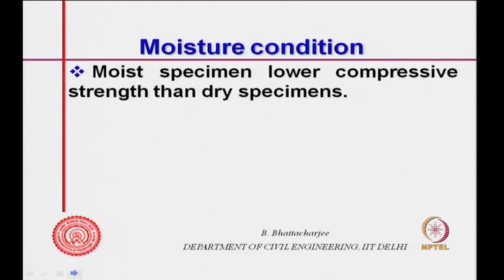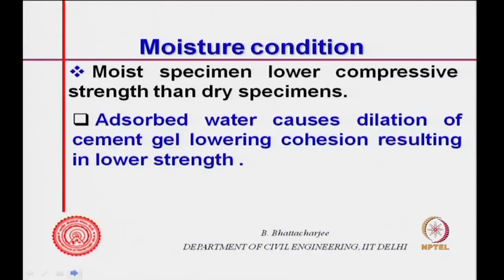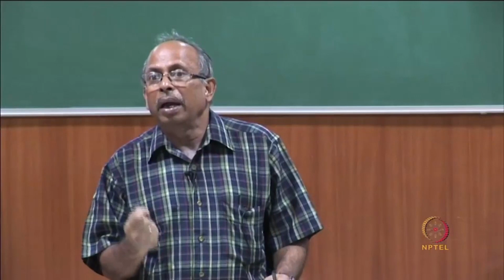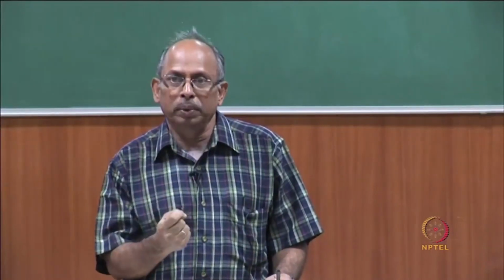Moisture condition: a moist specimen has lower compressive strength than a dry specimen. I just mentioned it the other day, because of adsorbed water. Now, what is adsorbed water? Water vapor can be adsorbed, and that actually forms a layer.